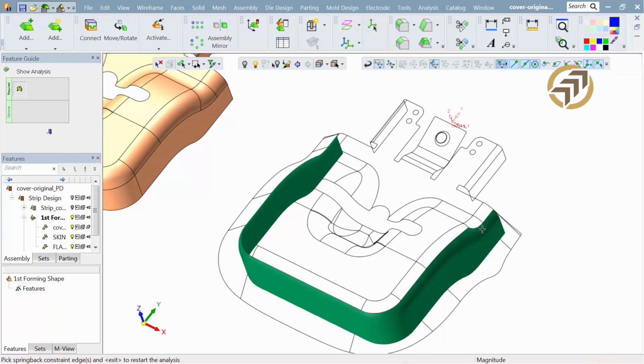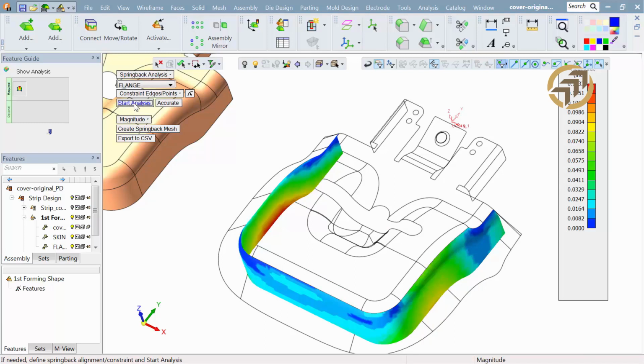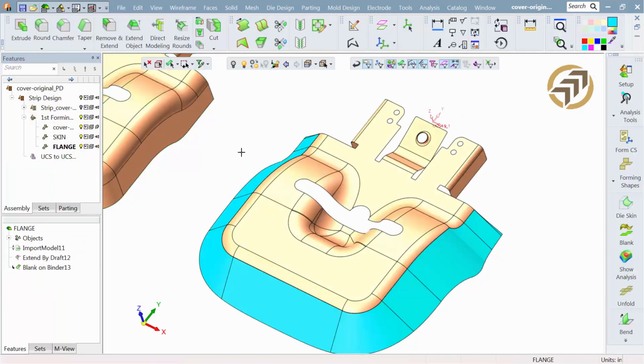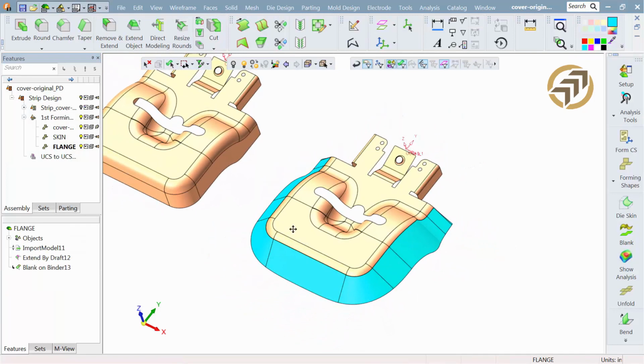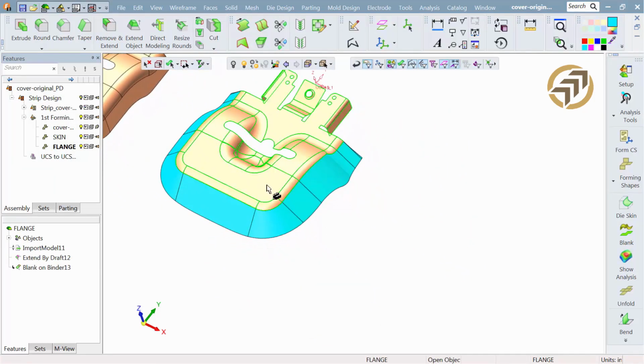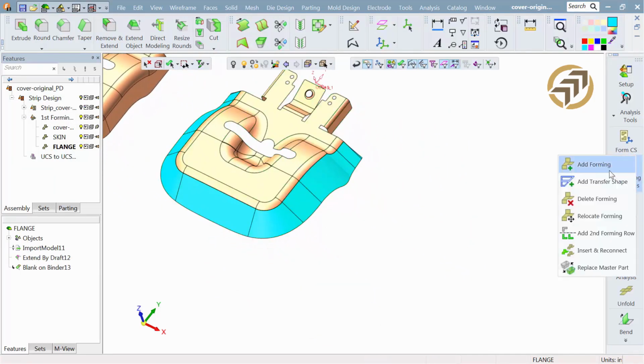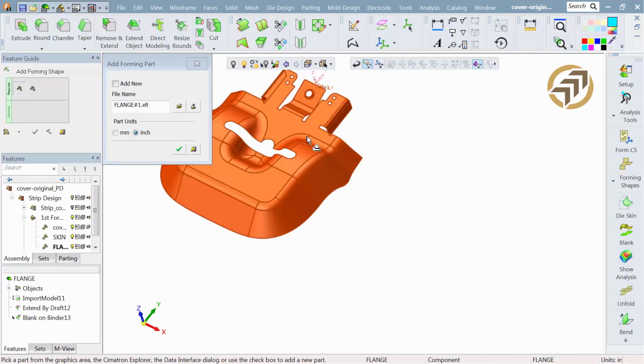Also, we can set this up so that we can look at some spring back. I'm picking a few areas. I'm saying hold on to that and let's see what possible areas of spring back may develop. It's based upon just that hit, just that development to 45 degrees. And there you saw in red an area that may show some spring back on the edge. We can take that information much further and actually adapt the forming tool as well to compensate for the spring back.